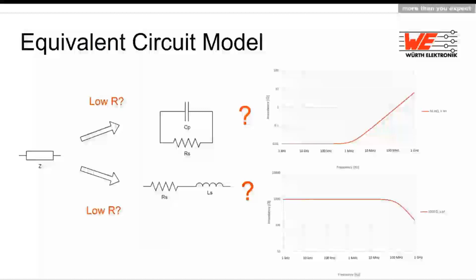After we have seen the measurements, we may of course want to create a model to describe the non-ideal behavior, also to use it in different simulation tools. But we have clearly seen 2 different trends. For high value resistance, we can see that at high frequency the impedance decreases, like in this graph. This is the parallel capacitance taking over as a low impedance path for the AC signal. If we look at a low resistance case, when we increase the frequency, we can see the impedance increase. This is series inductance that produces a higher impedance in the same path as the resistor. And this is also the same way our ferrites work in the application.